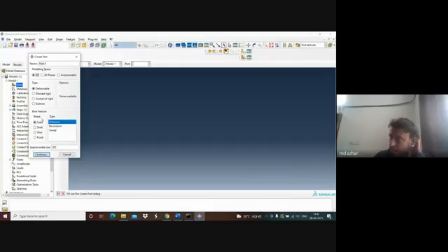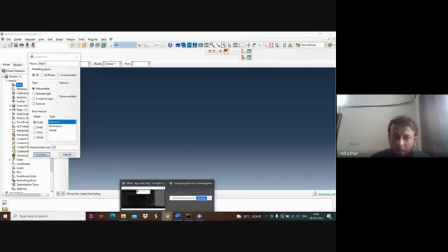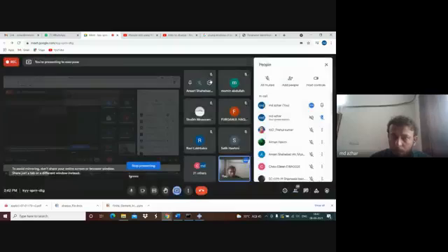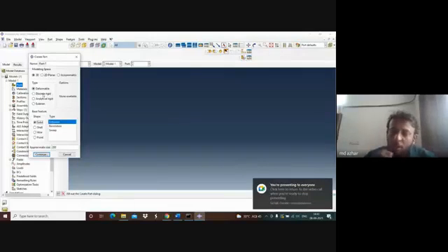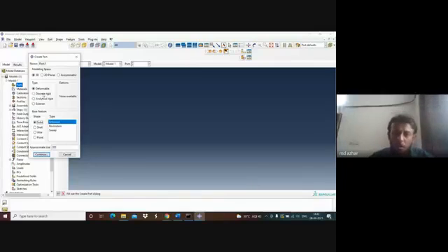And of course you can create a wireframe model that you should study in your CAD CAM. So these are the two terminologies you have to understand. You can still have a shell model in three-dimensional, but generally when people use three-dimensional, they use it for a solid model, not for the shell model. What is the difference between the solid and the shell model? If you want three-dimensional analysis, length, breadth, and height, everywhere, then you have to use a solid model. And if you want to do a two-dimensional analysis, then you can use a shell model.